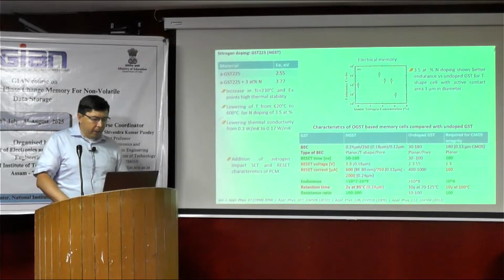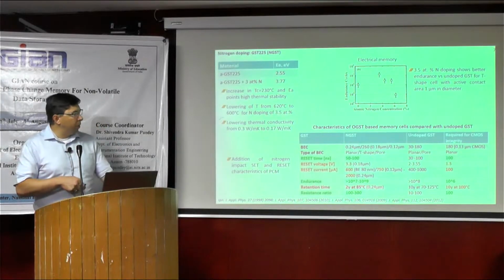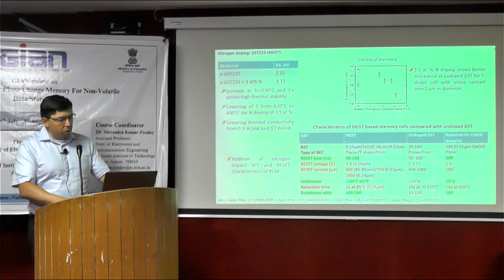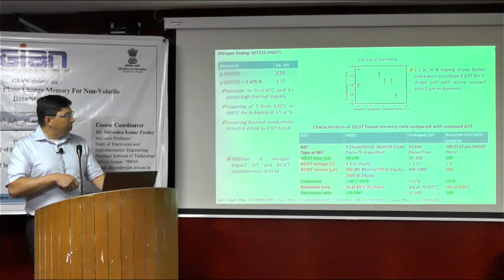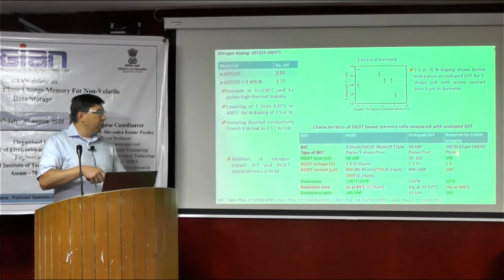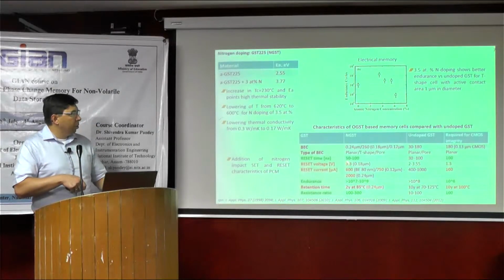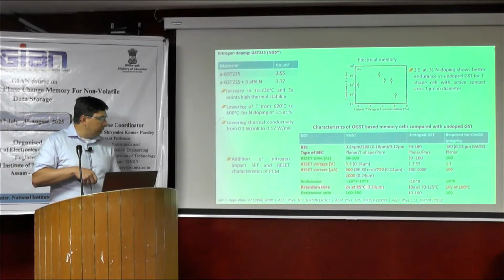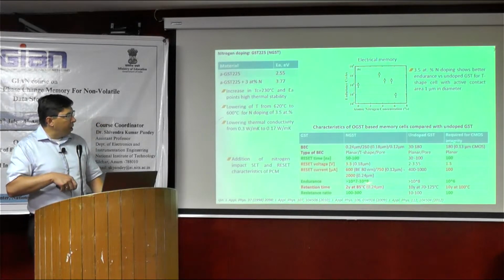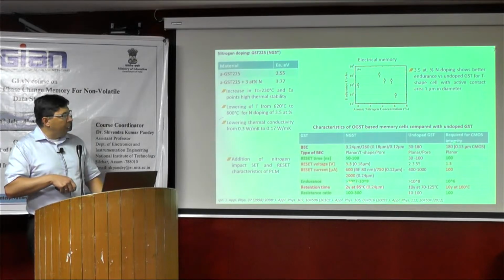However, unfortunately, phase change devices based on doped GST are not so good. They perform nicely, with a reset voltage on average of 3.3 volts, though the requirement for CMOS integration should be a little bit lower. It has nice reset times, in the range of 50 to 100 nanoseconds, but the retention time of such a cell and the endurance, as I said, can be improved here. This is between 10 to the 7 and 10 to the 9 for CMOS integration.